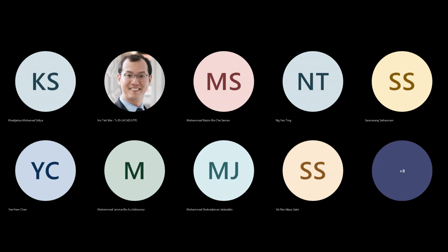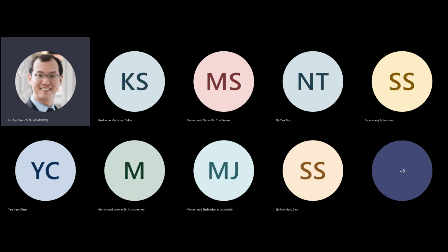So basically, what you are saying is that every time I want to create a multiplexer, I'll be using the NMOS and PMOS, both of them, connected in parallel? That is one way you can be using it. You can also use a multiplexer with this configuration. There will be certain instances where you'd favor this selection, and certain instances where this will be a little bit more acceptable. To a first order, if you're not going into IC design, it actually doesn't matter to you. To a first order, you can choose either one.